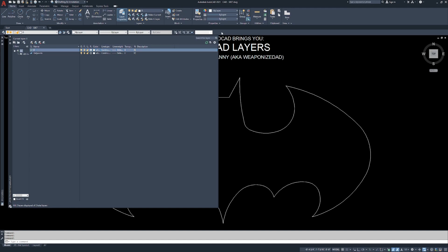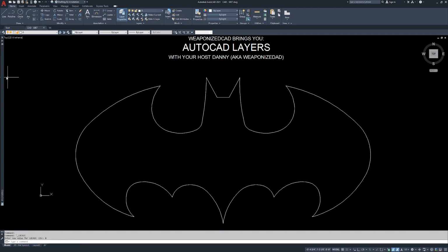The way that you lock it is you right click in this area, lock location. You can do all locked, unlocked. You can only lock your floating windows, which is what these are. You can lock your dock toolbars and panels, which if you dock them left, right, same thing. I'm going to unlock everything so I can slide this down just a little bit.